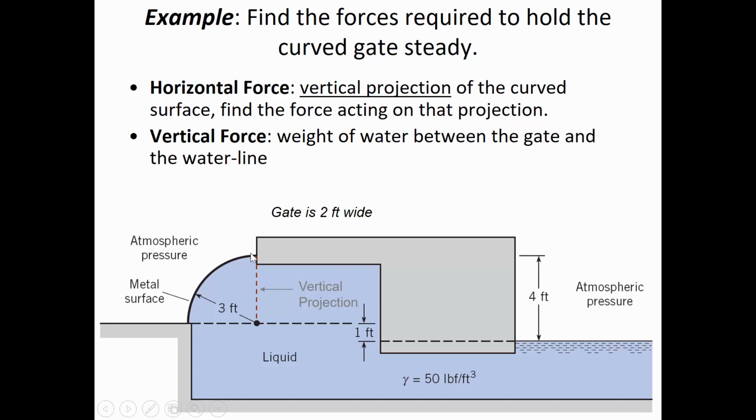So what's the direction of the force? Do you have an instinct for what the water is doing to that gate? What direction is it pushing or pulling on that gate? It's sucking the gate in. That's right. So this is a tricky problem because we normally think of the pressure acting against the gate, but here it's drawing the gate inward.